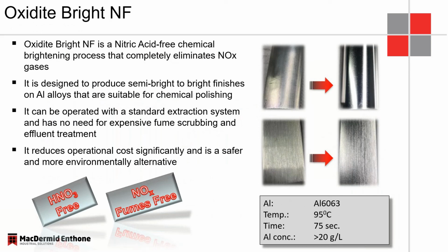I was touching on the nitric-free processes before, and after going through the mechanics of what happens in these solutions, we can understand why we will never achieve a very high gloss finish with these processes, because of the lack of the nitric acid and the oxidizing constituent of the system.